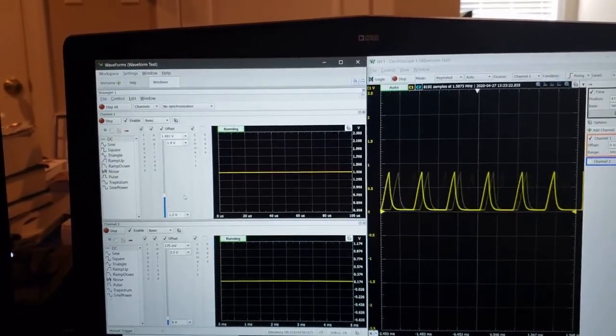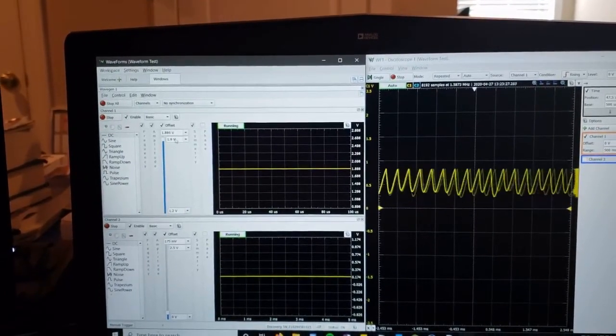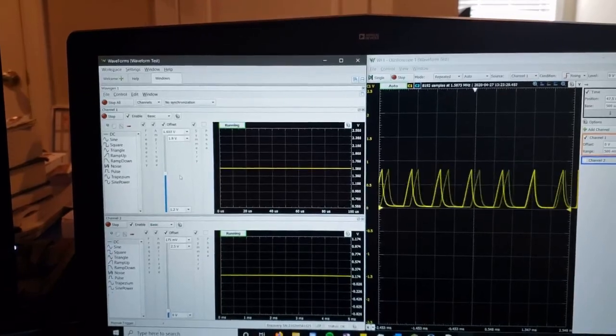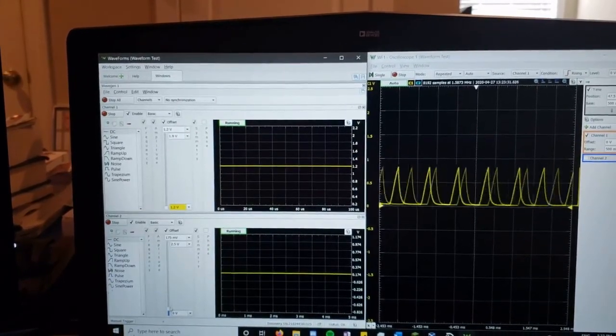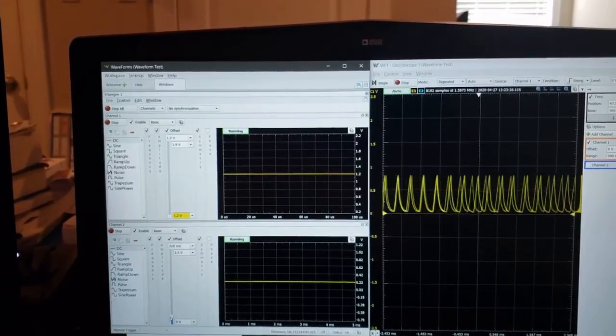As the PFET bias voltage was increased, the frequency was increased but the amplitude decreased. As the NFET bias voltage was increased, the frequency increased but the amplitude became too small.